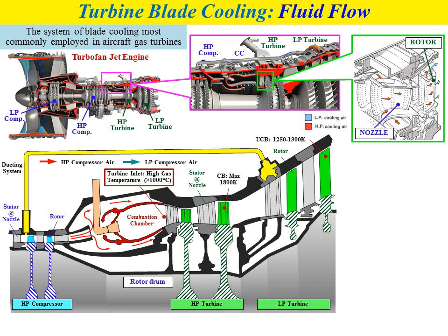In order to make the cooling process occur in the gas turbine engine, there are a few passages in the components of the gas turbine engine that allow the cooling air to pass through the components.